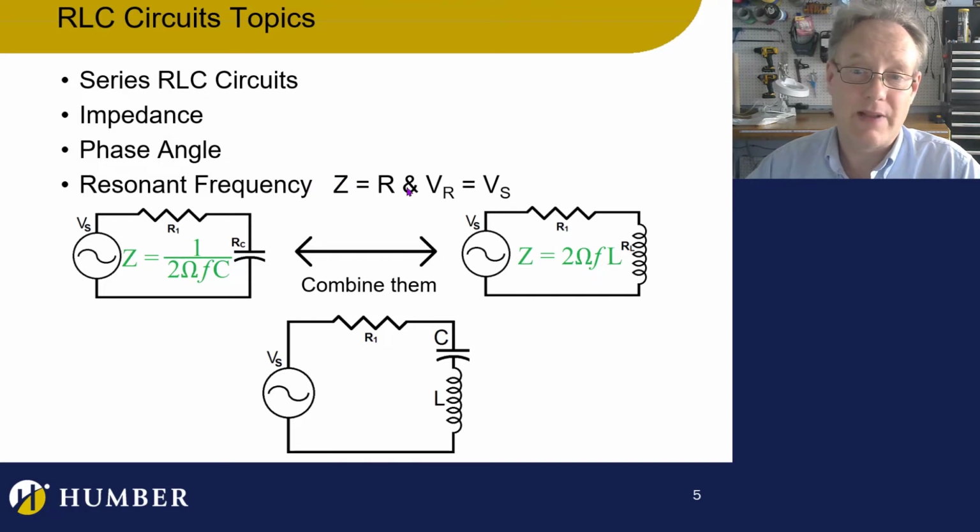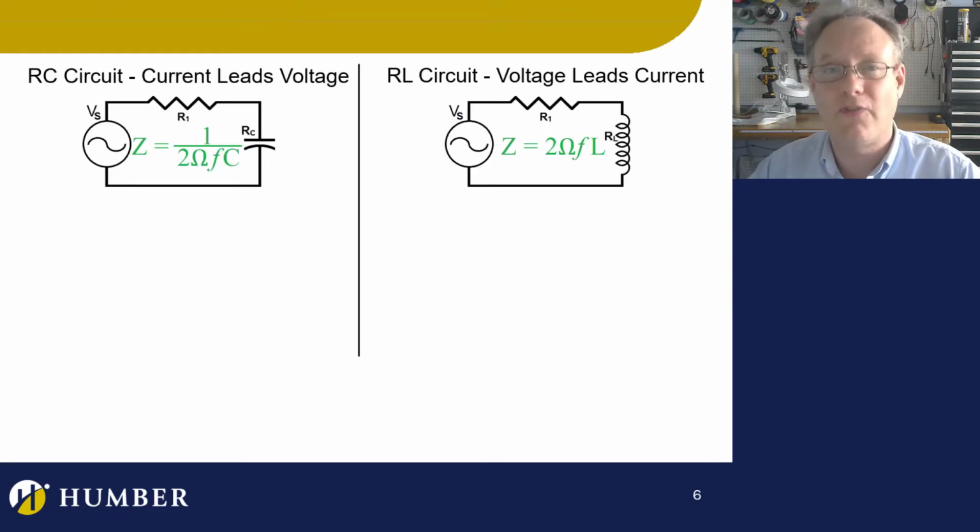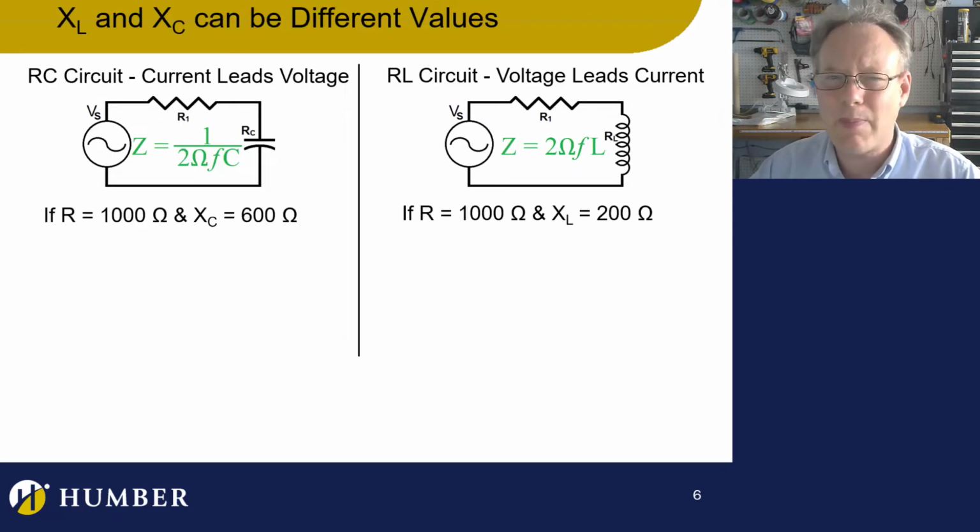But by the way, there's a question just like this on the exam. It'll be like, well, if a circuit is at resonance and the voltage source is 100 volts, what's the voltage drop across the resistor? 100 volts. Yeah, it's pretty cool. And you will see why that is true in a minute. Let's move forward and take a look at just a little bit more review.